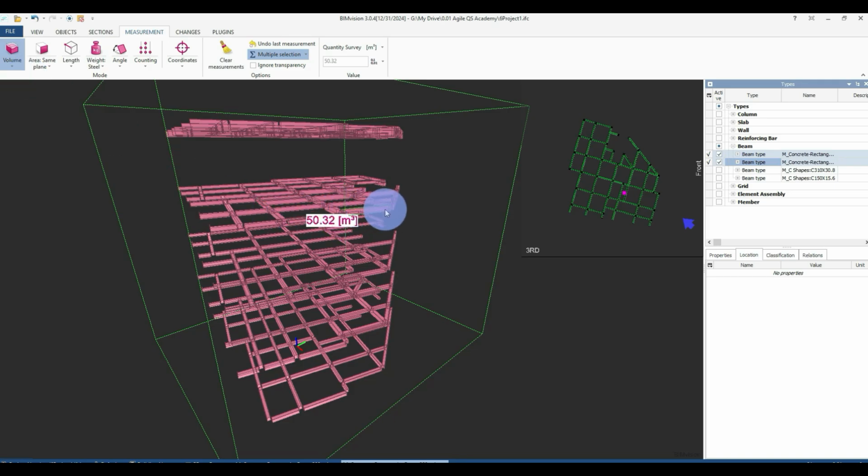So if you can do the math, you can take the whole concrete that we've calculated, then you get the total, then you take our reinforcements, you divide by the total concrete we calculated, then you can get the ratio of your reinforcement, kilogram per cubic meter of the concrete, and you can have a very low.